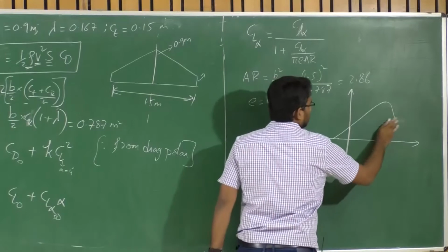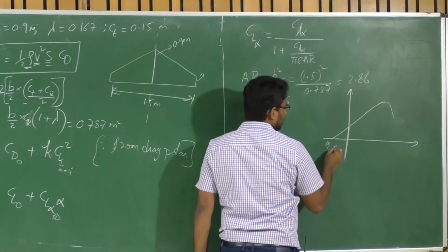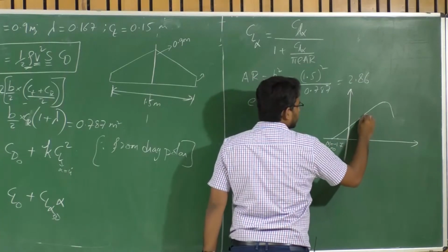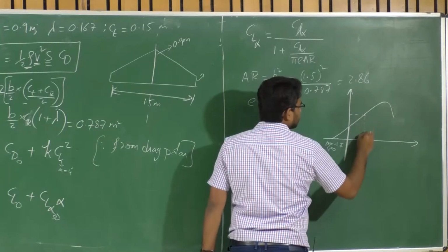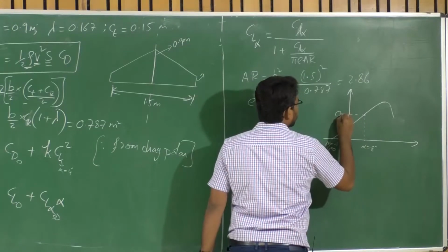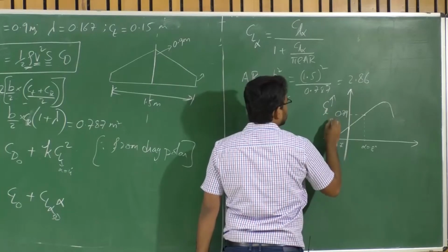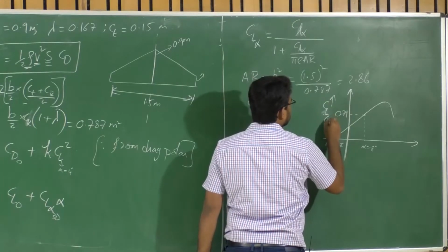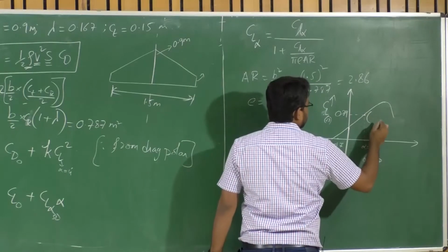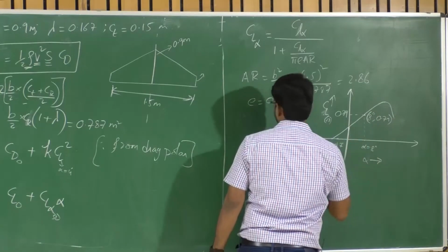Okay, so alpha at which CL is equal to 0 is minus 1.7 degrees, right? And then CL at alpha equal to 8 degrees, the corresponding CL value is 0.79. This is the CL 2D case, CL 2D and alpha. So the coordinates here are 8 degrees and 0.79.